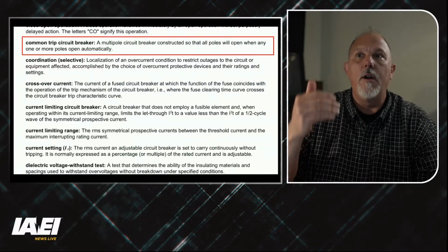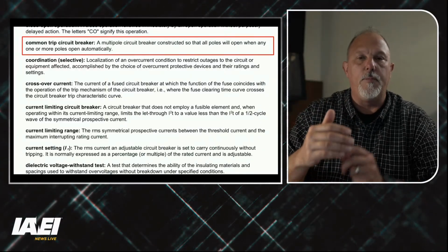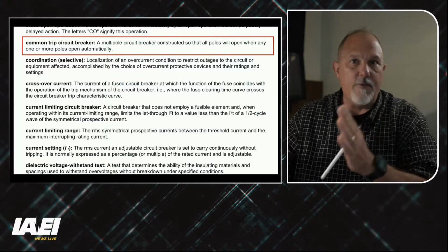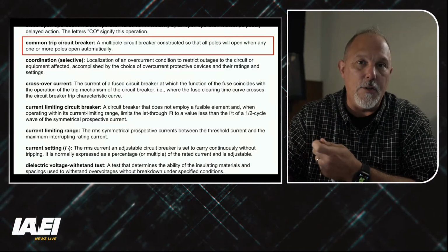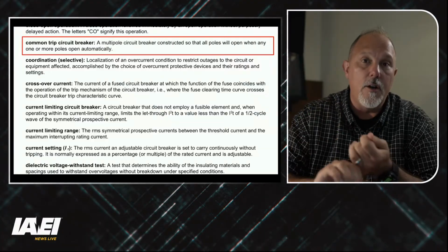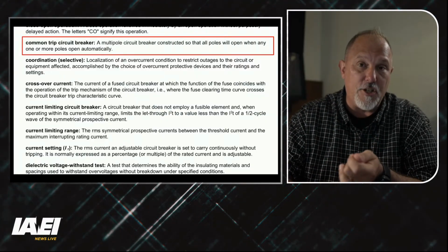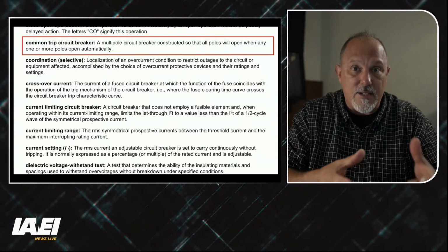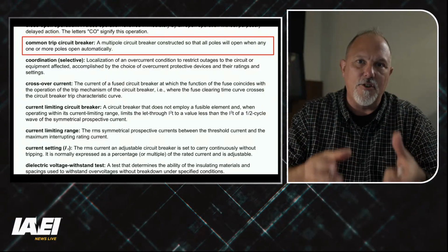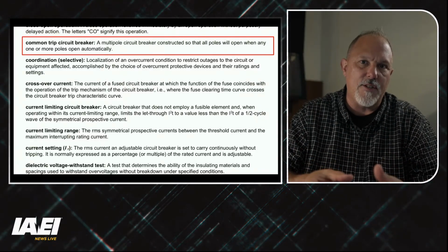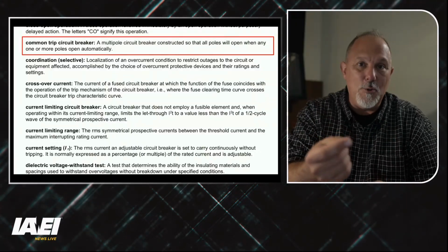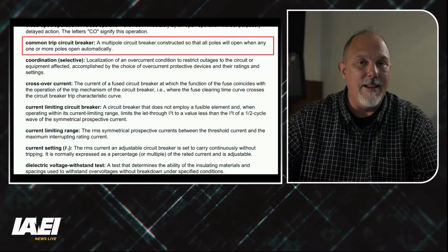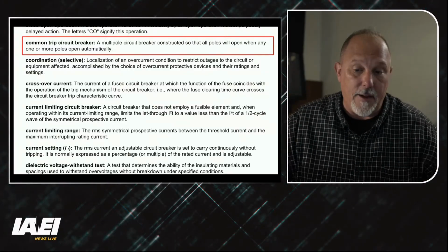And just think, if you know that the circuit breaker opened for currents less than a certain number because currents greater than a certain number were cleared by the current limiting fuse, those high fault currents provide the current limitation for the circuit, but also for the overcurrent device itself, for the circuit breaker and the assembly within which it's installed. So that current limiting nature of taking that current off very fast performs the function, but it gives you the awareness of what magnitude of current that circuit breaker had to have seen. It's a ballpark figure, but hey, it's better than nothing, in my opinion.